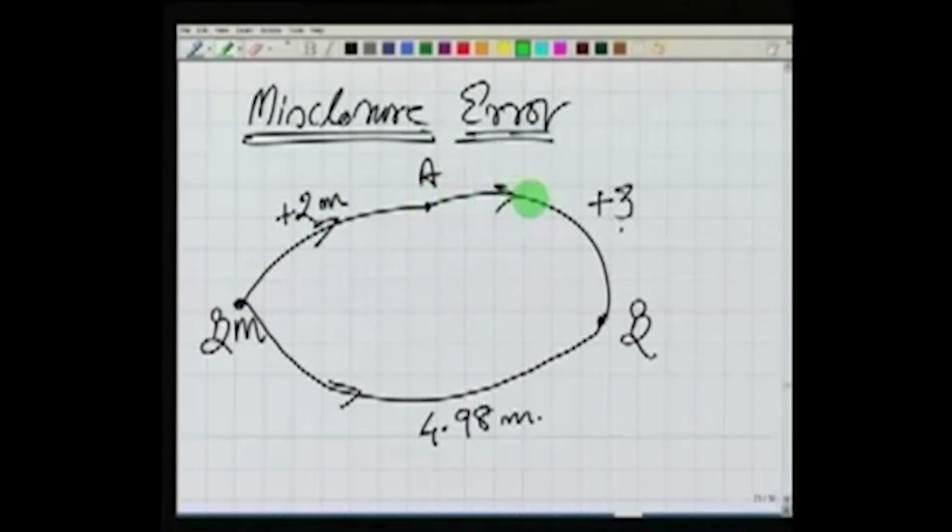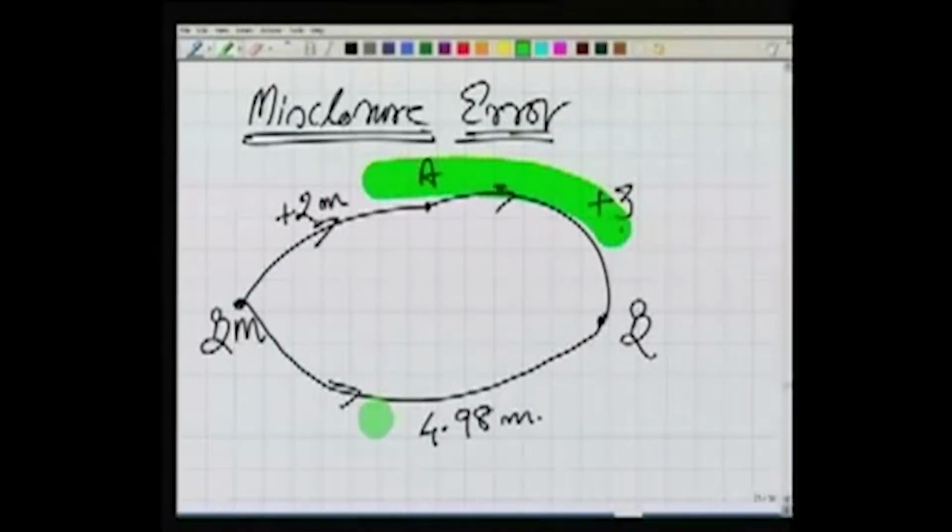It indicates that while we are taking the observations from two routes, one route here, this plus this, I found the RL of this, then the second time I am doing it directly here, I am finding the RL of this, and the RL in both cases is coming different. Is it possible? On the ground it is a single point. It should have one RL, but we are getting two different values, through this route and through this route. It's not possible.